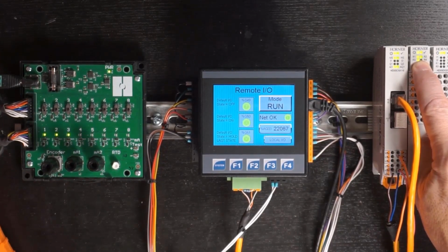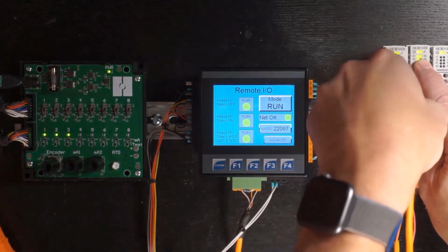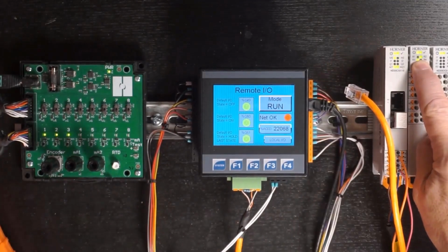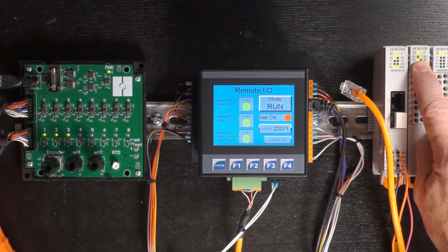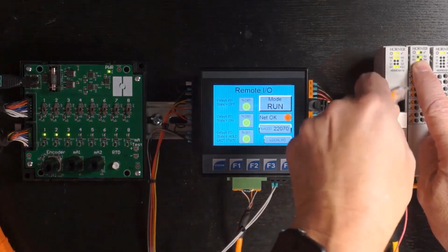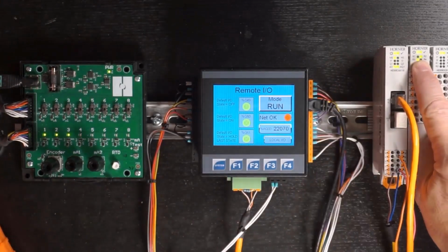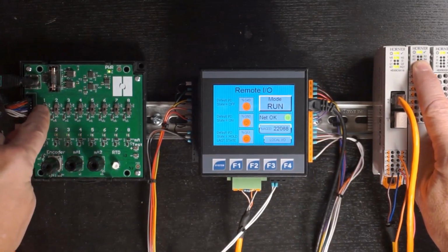In addition to the PLC going into stop mode, we could also lose network communications. Next, we will pull out the cable connected to the network. Once we do this, we can see that we have quickly lost communication, shown by the flashing LED. Our first output is off because of how we configured it. The second output is on, and the third output has held its state. Now we will plug the cable in again to resume communications. Once again, the outputs are following the switch.